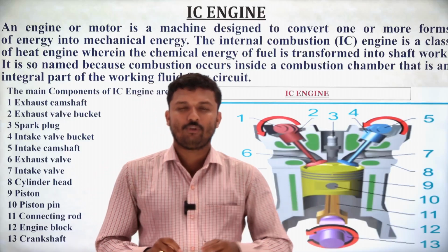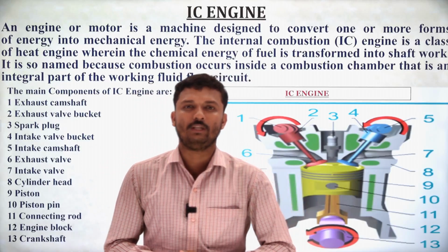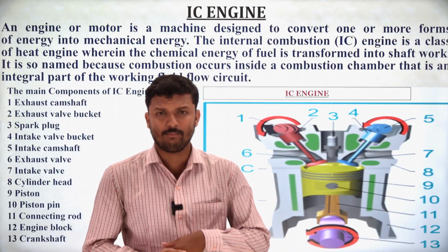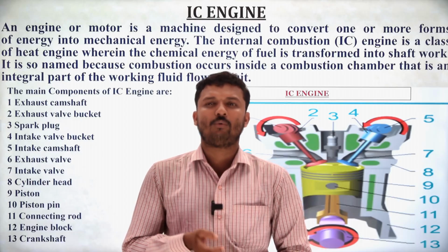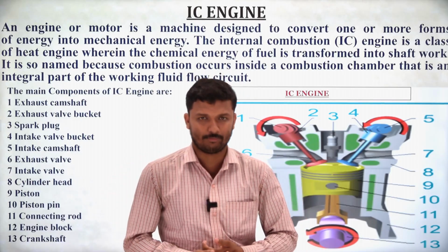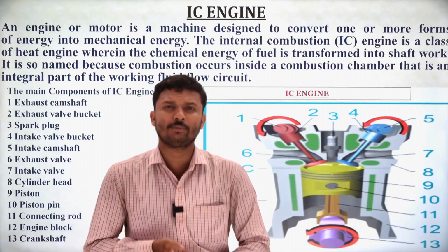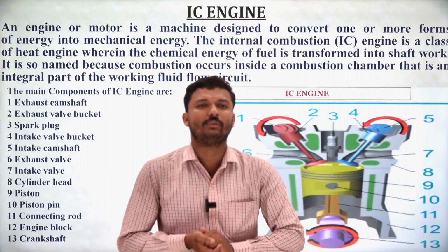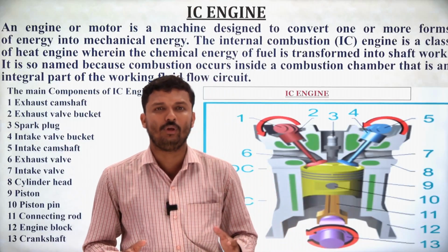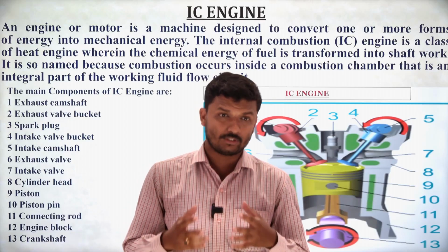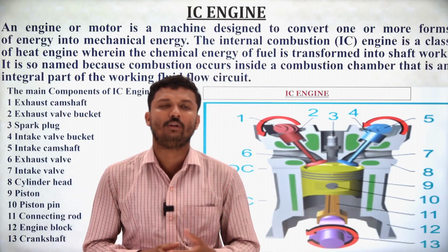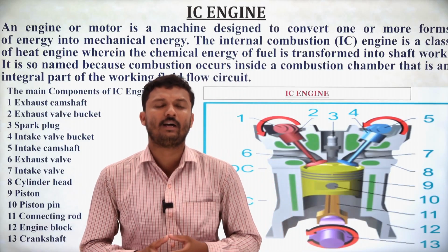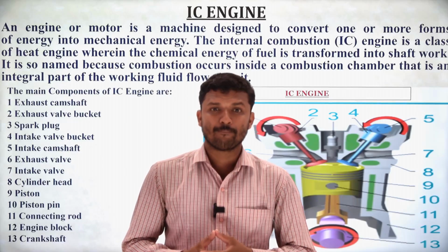So today we will discuss particularly the automobile engine, the IC engine, the internal combustion engine. An engine or a motor is a machine designed to convert one or more forms of energy into a mechanical form of energy. The internal combustion engine, or IC engine, is classified as a heat engine, where the chemical energy of the fuel is transferred into shaft work, the mechanical form of energy. It is so named because the combustion occurs inside the combustion chamber, as an integral part of the working fluid flow through it.